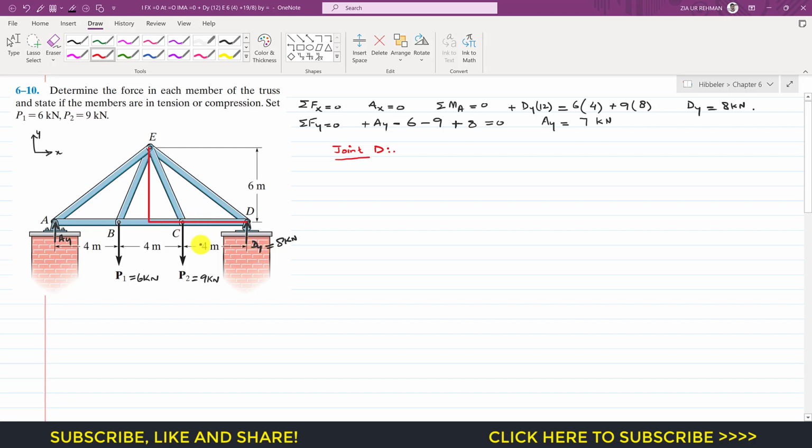The base of this triangle will be 4 plus half of this length. Since this whole truss is symmetrical about this line, we can find this ED length by applying the Pythagoras theorem. So we can say that the length of ED member square will be equal to this square.